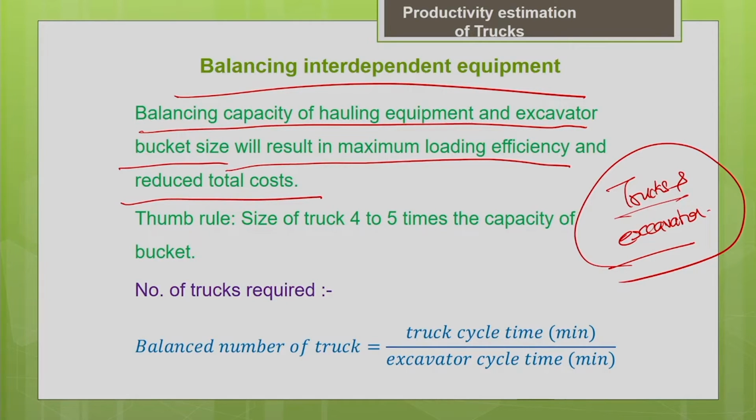That is why I told you, based upon the studies, the truck capacity should be 4 to 5 times the bucket capacity.